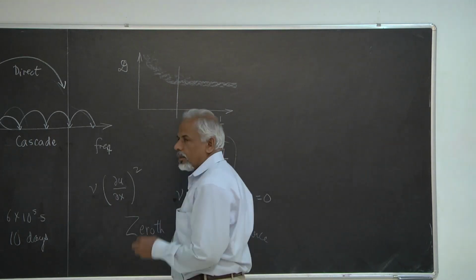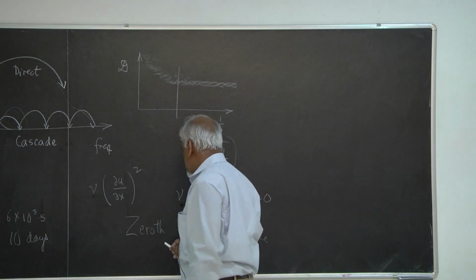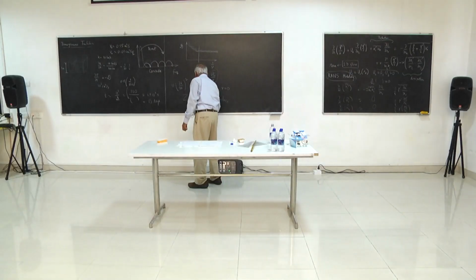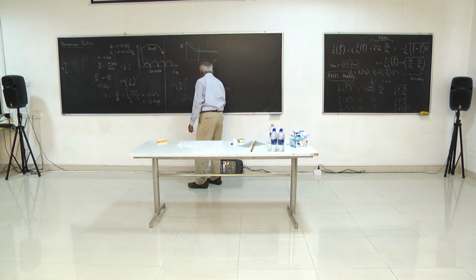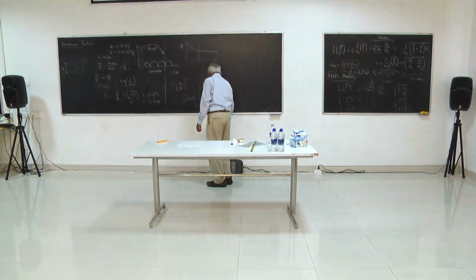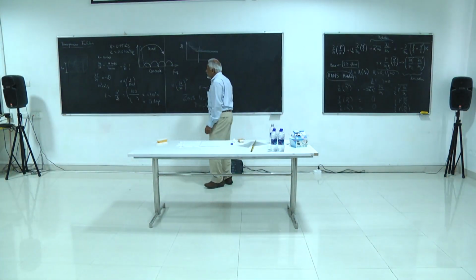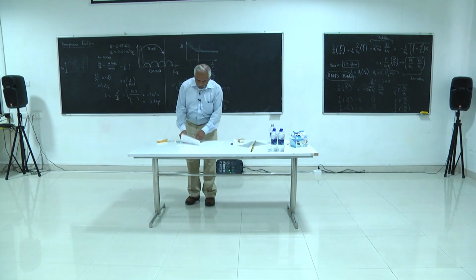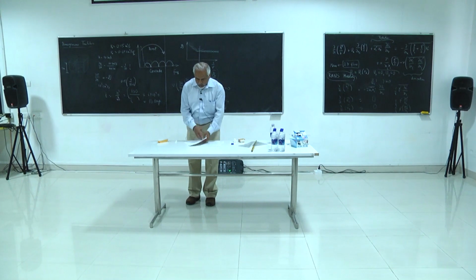Basically it is the so-called dissipative anomaly. The anomaly is that when the viscosity goes to 0, the dissipation does not go to 0 but remains finite. Okay, so we'll leave it here, and when we come back, we will talk about the homogeneous turbulence proper.